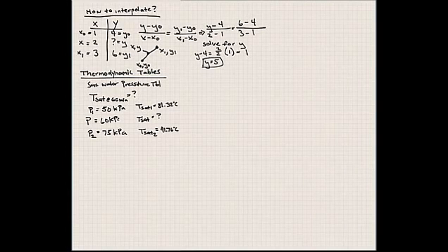And keep in mind, again, we don't have this value in the book. So we don't have this value in the book either. So we're using the surrounding data and assuming a linear behavior so that we can solve for this saturation temperature at that pressure.